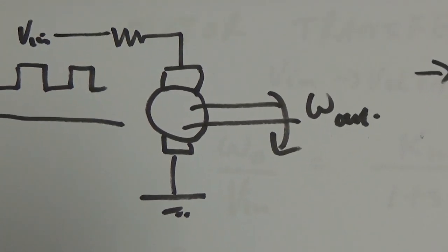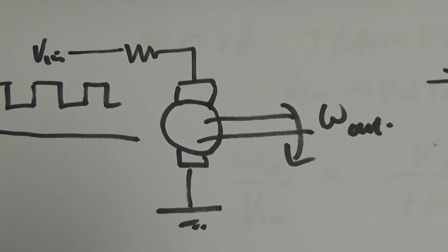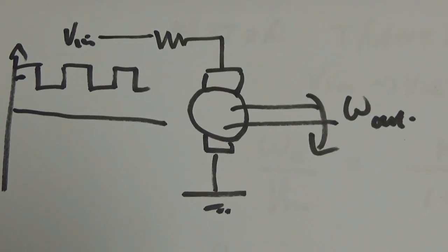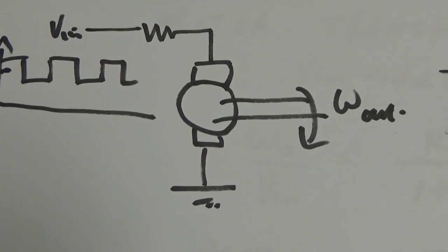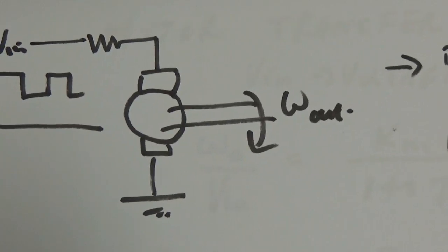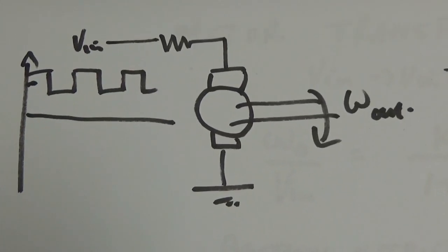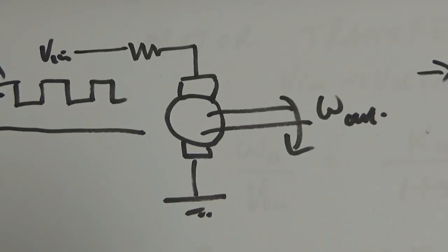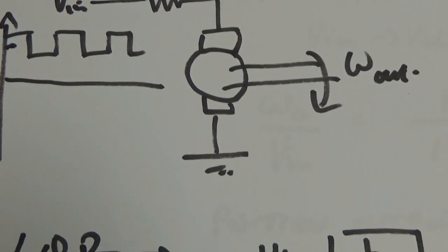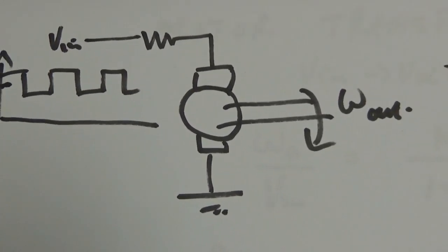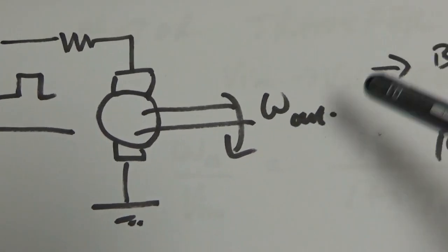You may be wondering why we're measuring the velocity, not the position, because this is a position controller that we're dealing with. And the answer is, it's a bit too difficult to get RLS to work with position, because to get from velocity to position is an integrator. Anything with an integrator in open loop means that for any DC you put into it, it just flies off to infinity, off to saturation, and you get pretty rubbish results, really. So it's easier to identify the transfer function to the velocity, angular velocity, and not to position.